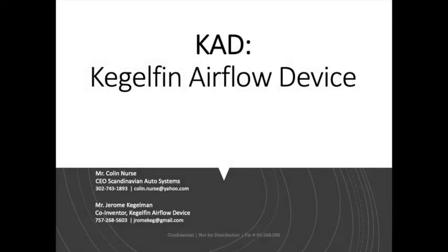What follows is a description of the Kegelfin airflow device, or KAD. The KAD utilizes the Coandă effect to increase the ambient air pressure in the zone immediately behind the trailer when it is in motion. In other words, the zone outside of the closed trailer doors is pressurized. This phenomenon reduces the energy, gas, diesel, or electric, needed to move the trailer and keep it in motion.